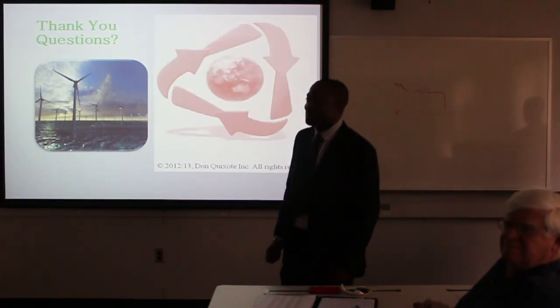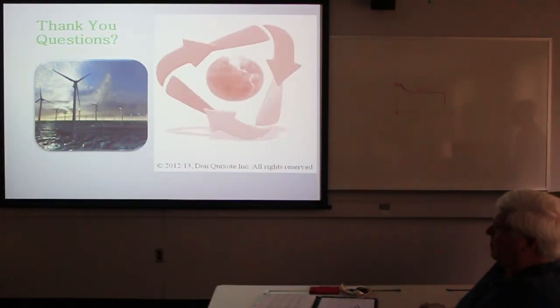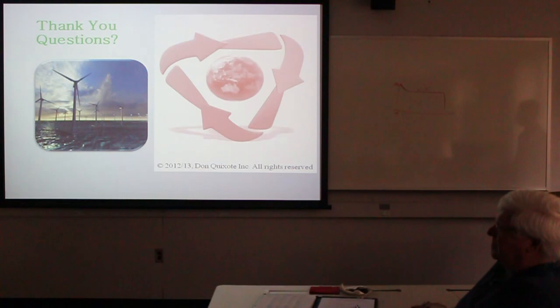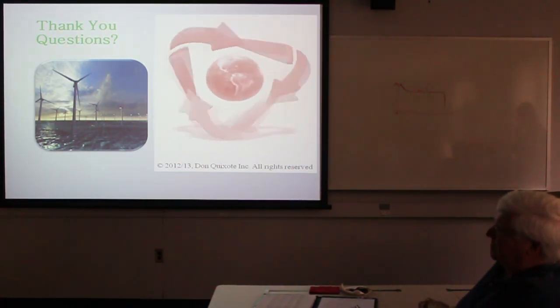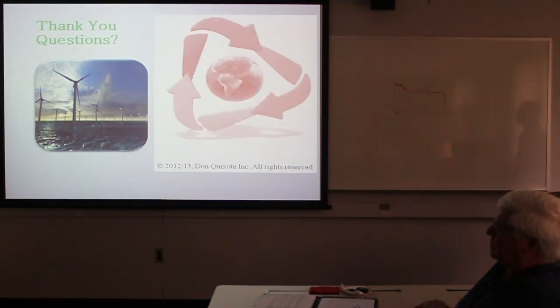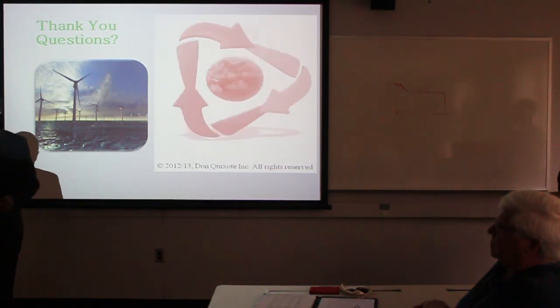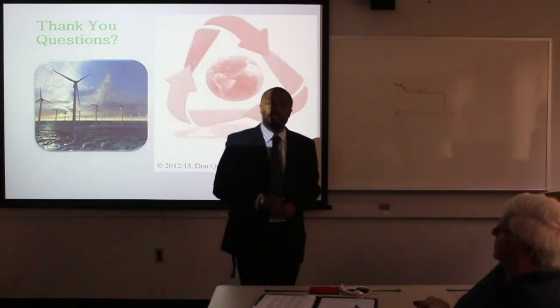Did you put some weight in the bottom? Yes, we had to balance it out a little bit, because initially they were floating pretty well, but once we added the motors, since the motors were only in the X and Y directions, we had to compensate. So we added a little mass, approximately 2 pounds, on the opposite side to reach our stable state before testing.